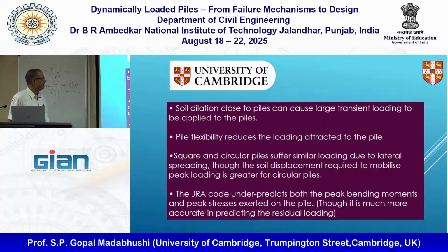So in summary of single pile, what have we learned? We are very sure that soil dilation close to the pile causes this transient loading. That's why you're getting those suctions and differential earth pressure, pore pressures.